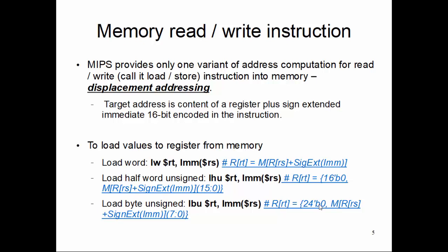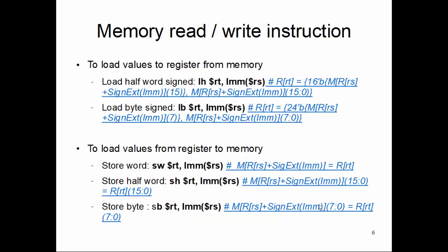To do that, we need to make a little more complex operation, at least notation wise, a little bit more scary in the expression we are giving in this area, but be with me and try to understand each part of it. So what load half word signed really does, first of all, it does the memory address computation. That's common for everything, so don't be worried about that.